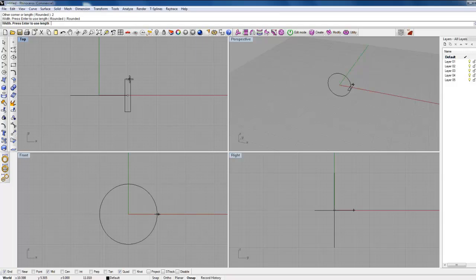Well, it's not obvious, is it? But for what I've got in mind, we'll click 7 and enter. Now, if you can see, it's put a cross section there, but because we clicked the rounded, it's asking us now, if we zoom in there with the scroll wheel, what shape we want this. And as you move, you can see that cross section curve moving. So you just get to something that you like, and then left click on it.